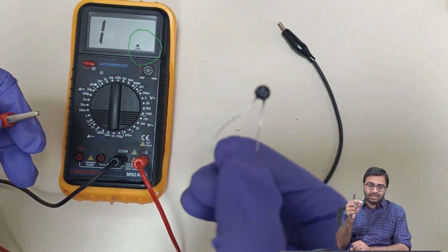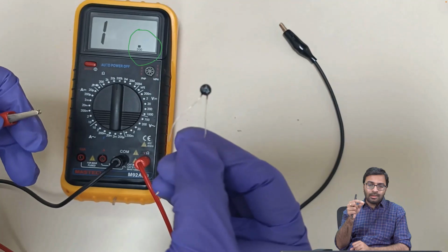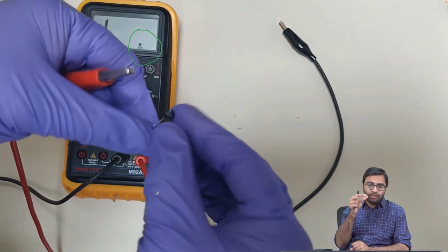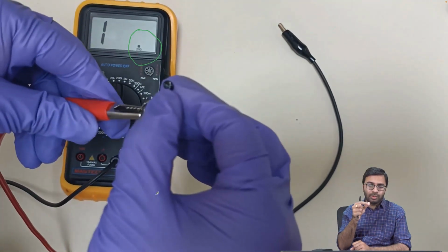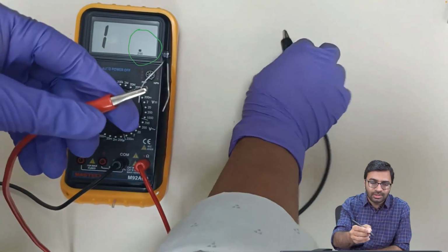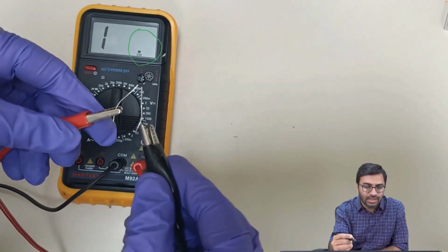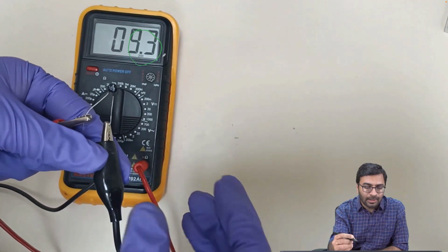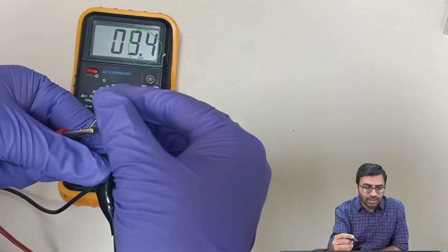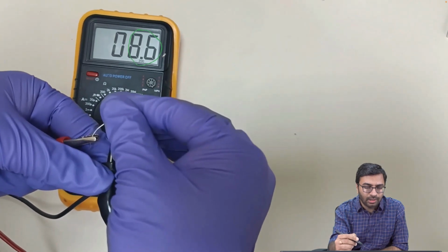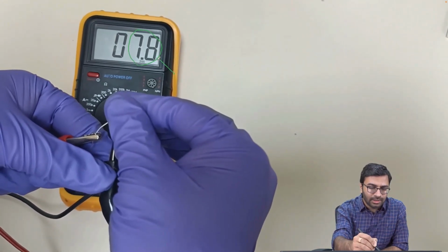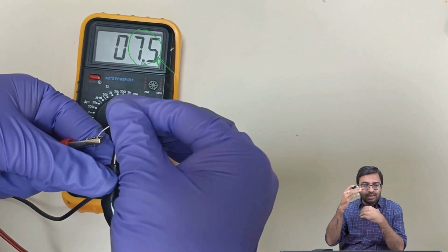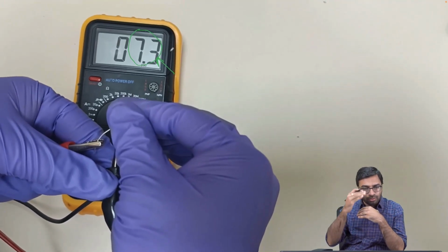and then the moment I have touched the sensor, the moment you touch it, in the video you will see that the resistance will start dropping, right? So initially it's like 9 kilo ohm, and then when you touch it, the temperature around it will increase, and see the numbers start decreasing. That means it decreases from base to lower values.